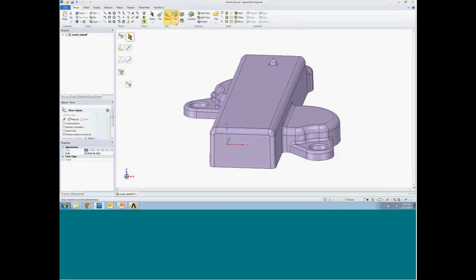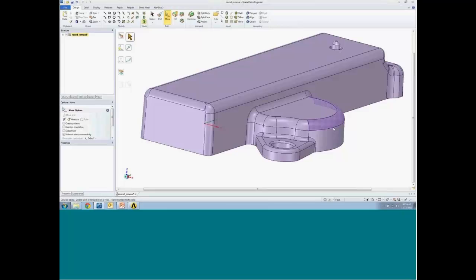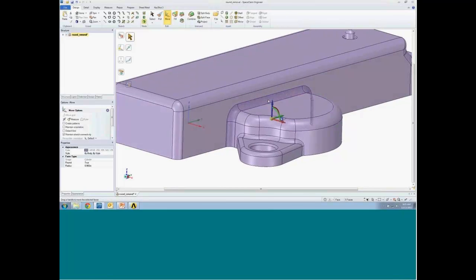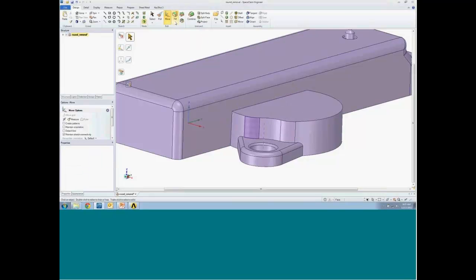If you want to fill in a hole, this is where you use that tool. It works extremely well on things like rounds for simplifying a model. So I could double-click, intelligently gather a chain of rounds, or chains of rounds, plural, and fill those in and wipe those out in seconds. So SpaceClaim does a remarkable job at simplifying things.